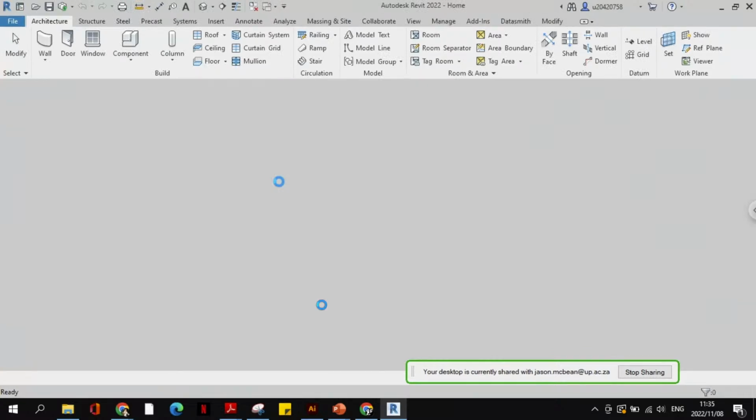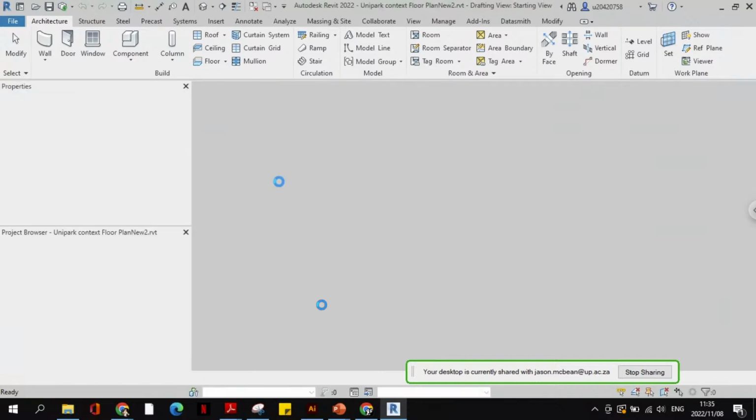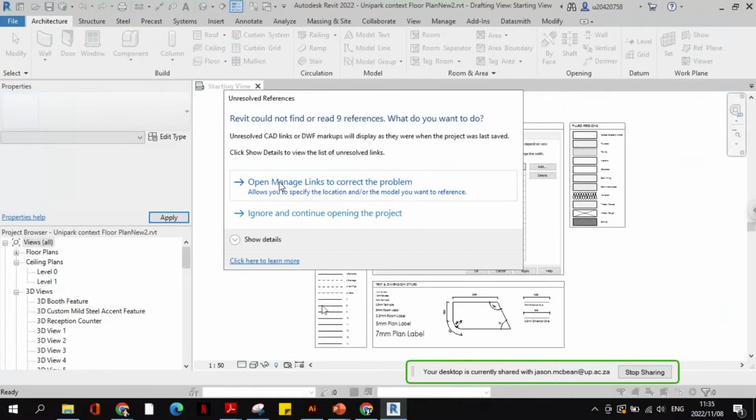So play with your settings. Leave it in maybe. Just change your curtain panels so that they're solid. I actually need help with those curtain panels now. What do you mean? Because if it's glass, it's not going to look like a ceiling. You have to change the panel, the system itself, to a solid. Okay.